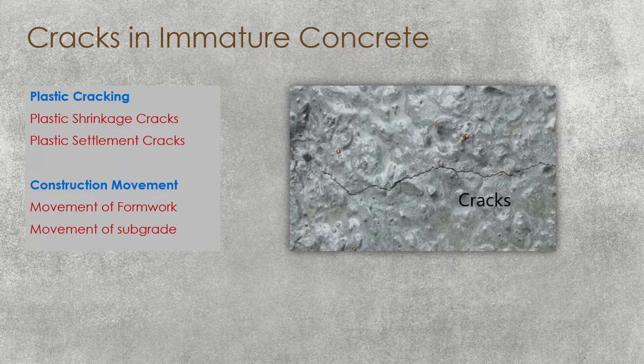Movement of the subgrade: same as the formwork, the subgrade of the foundation where we place the concrete needs to have zero settlement. If it is settled, there will be issues, or else the settlement should be uniform all over the place. Now, when you consider a thick concrete, you may be pouring the concrete from one end to another.